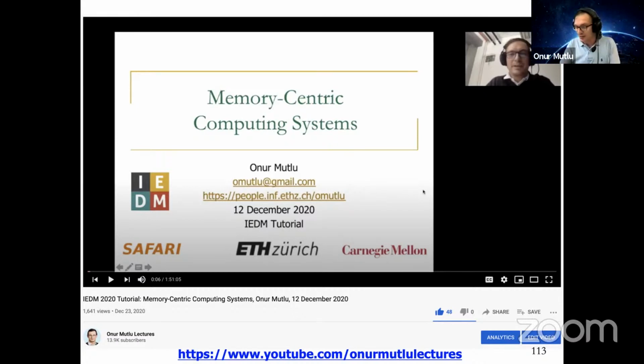So there are two issues. First of all, DRAM memory directly gets exposed to data structures, system data structures, programmer data structures, any user data structures, everything. So you can actually destroy data directly. And the second is, in DRAM, traditionally, there has not been much error correction because people thought DRAM is the perfect memory technology and you didn't need a lot of error correction. In fact, consumer systems have no error correction. Increasingly, people are adding error correction, but people are also finding that you can circumvent the error correction to do RowHammer attacks. So basically, DRAM is very special because of these two reasons. And as a result, you can launch RowHammer attacks.